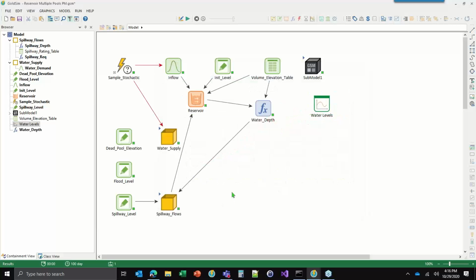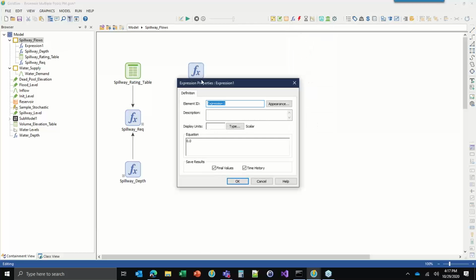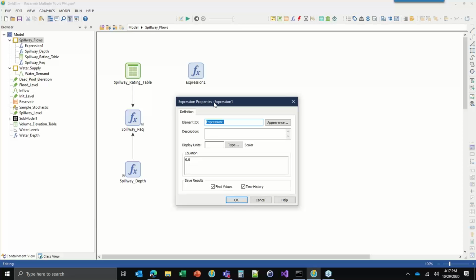So these can cause problems, especially if you have many ponds or reservoirs connected to each other. So what you want to do here is put a check on this, where you say we cannot discharge any more than the volume of that slice of water that is sitting above the spillway elevation. So I'm going to put in here a value that's referring to the volume of water above the spillway, if the water level rises above it.